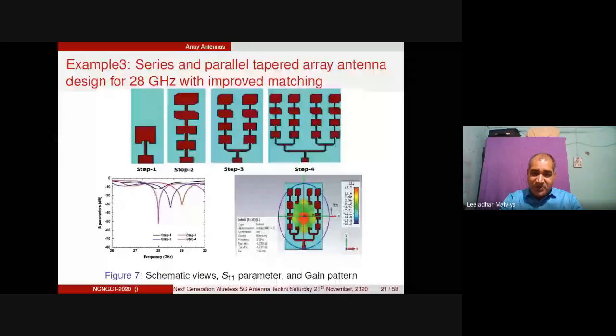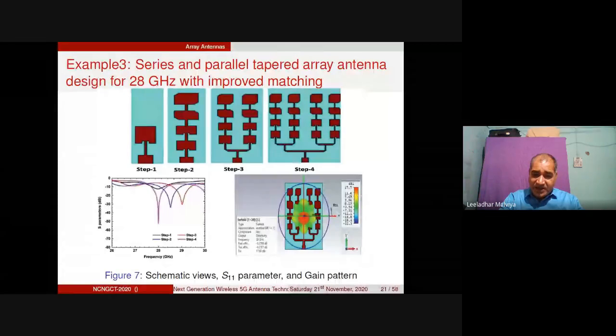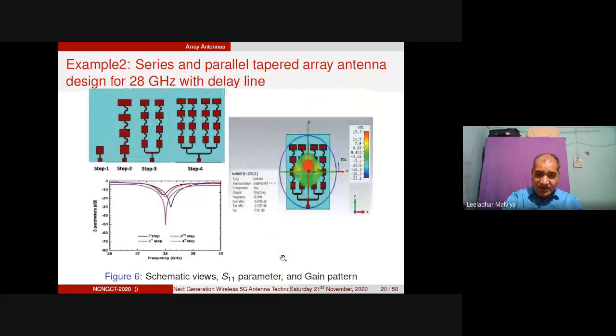So finally, by doing this design, we have targeted the radiation pattern at the center. Yes, you are able to find this at the center here. Again, the back lobe is controlled here, but a slight change in gain and directivity can be seen here, right? And if you look at radiation efficiency or the total efficiency, that is not affected in comparison to design 2, right?